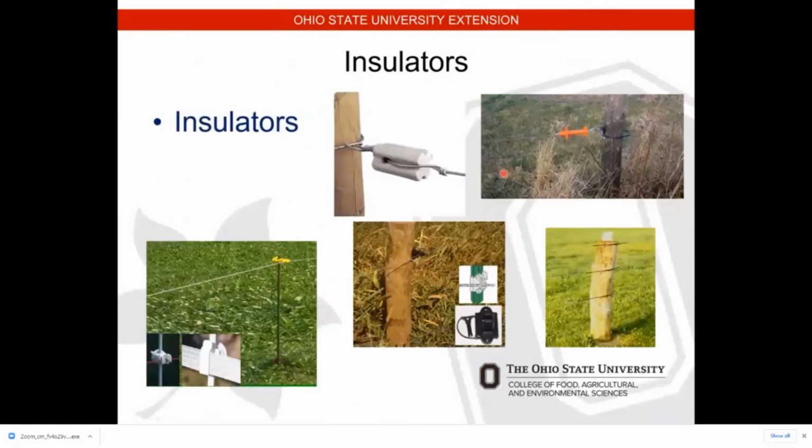Insulators, again, a whole big variety of selections, colors, and types out there. These insulators, these little tubes that wrap around the end of your corner posts, they do work. The only downfall is that over time, they will start to crack. I've got some that are 20, 25 years old, and they're starting to crack and short out on the posts. So what I'm doing is coming back in and putting these bullnose insulators in.